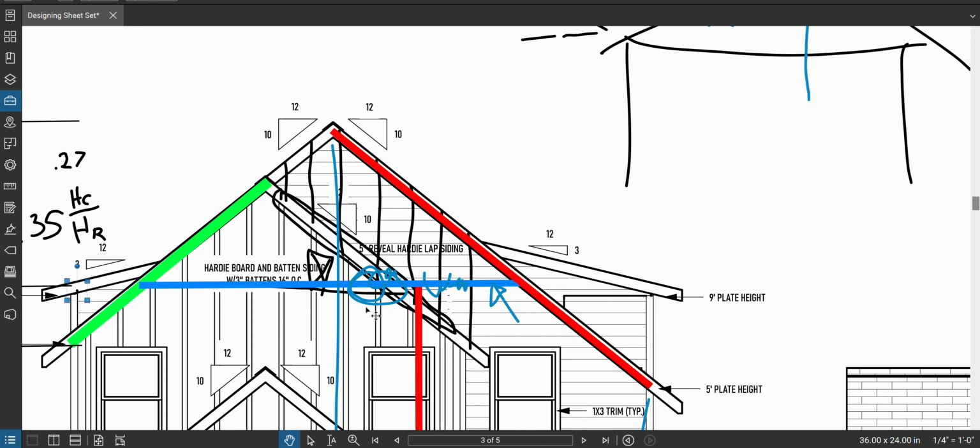This right side is the bottom stud wall. Spruce pine fir. The left side was the face mount hanger. That sounds good. And the beam material is probably southern pine. This is what it's hanging on is southern pine. Matters a little bit, but not a ton.